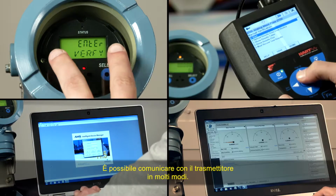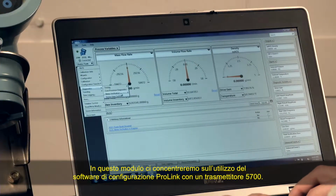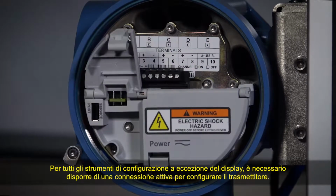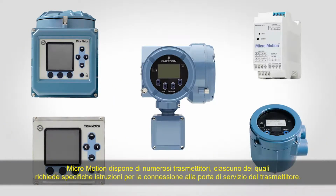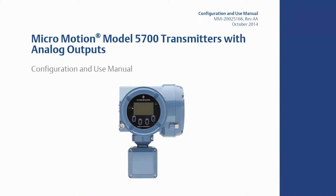There are many ways to communicate with your transmitter. We will focus on using the ProLink configuration software with a 5700 transmitter in this module. For all configuration tools except the display, you must have an active connection to configure the transmitter. Micro Motion has a variety of transmitters that each have specific instructions for connecting to the transmitter service port. Please refer to the Configuration and Use Manual for your specific transmitter for the complete setup instructions.